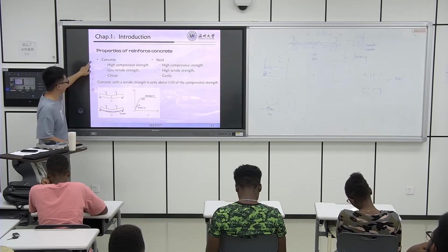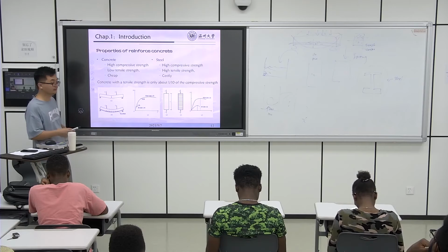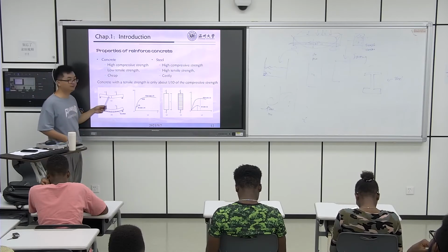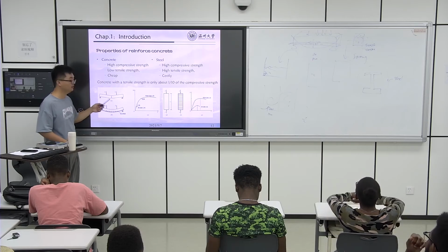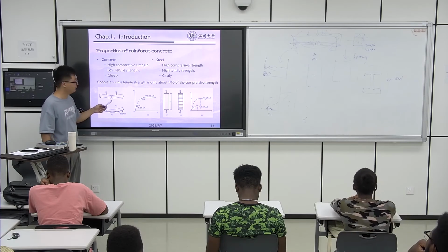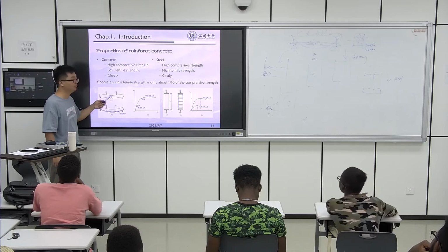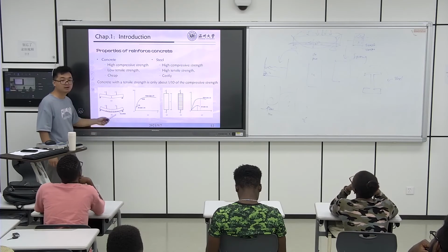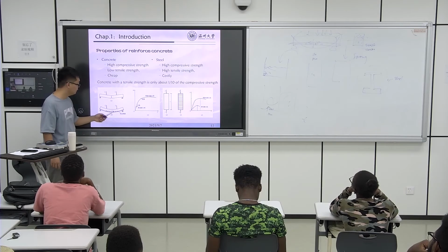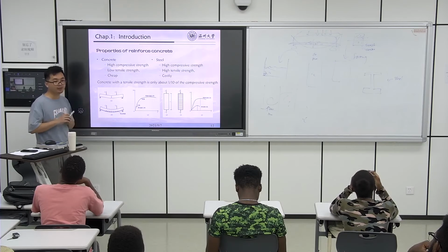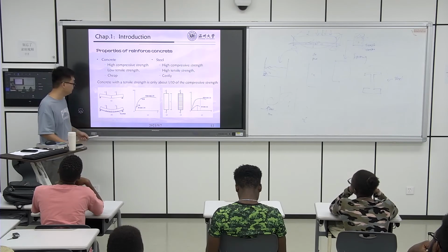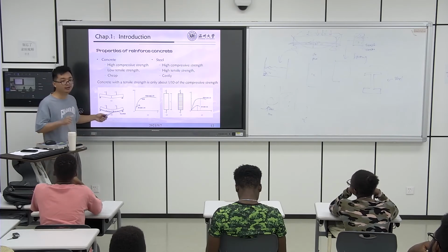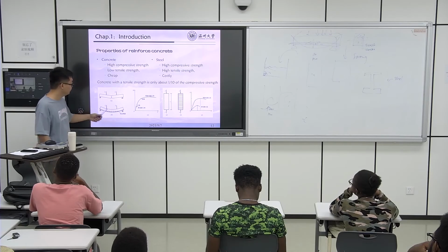Yeah, okay. There are figures in the last sheet. For these figures, there are no steel bars under the load. The crack will develop at the bottom of the beam, and quickly the beam fails. But if we use steel bars, the tension is resisted by the steel bars, which can prevent the crack development. So they will improve the character of the beam.